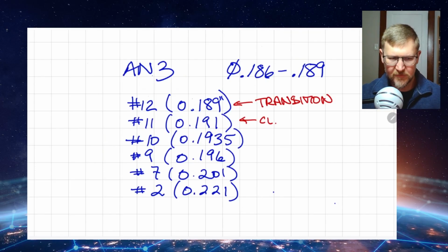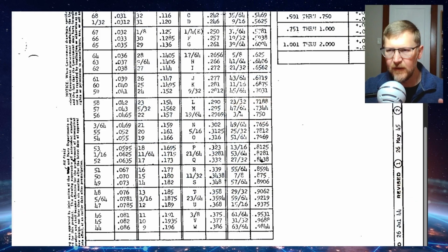It's probably worth stopping for a second to talk about tolerances for fasteners, not just fasteners, but holes, sorry. When you're drilling a hole, there actually are tolerances that you have to account for the drill bit itself and the manufacturing process. If you're unfamiliar with what those standards are, there is another national standard out there which is pretty much out of date, but it still holds. People still use it for reference, so I'll show you that here.